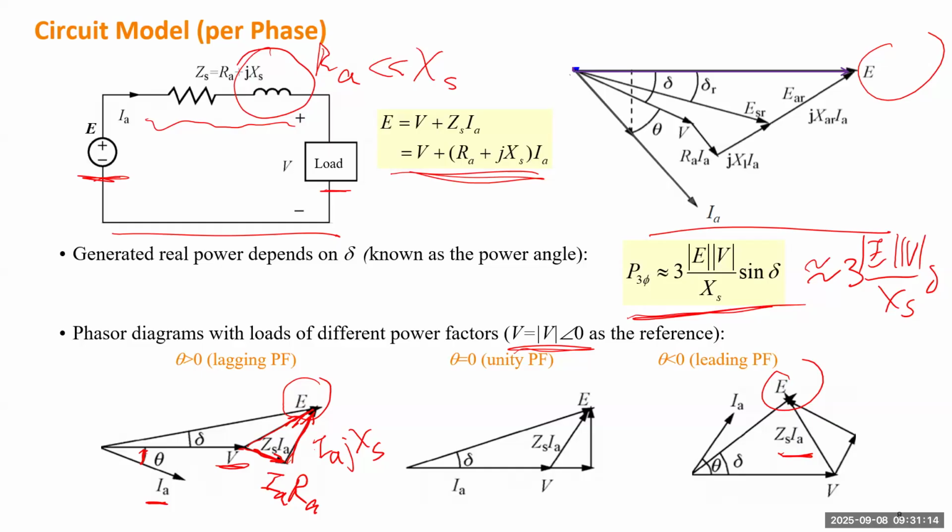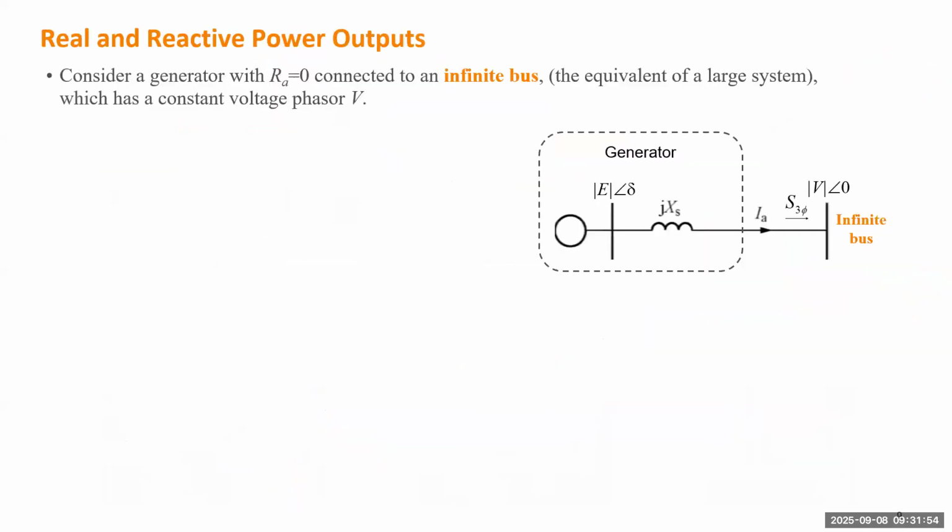It's okay for this circuit to have a single voltage source connected to a single load. But if this voltage source is a generator that needs to revolve synchronously with the system, the load also needs to be another synchronous machine, either a synchronous motor or a synchronous generator, so they together can have the synchronous speed. It's hard to have a synchronous generator connect to a non-rotational mass or machine. So it's better we connect to a system.